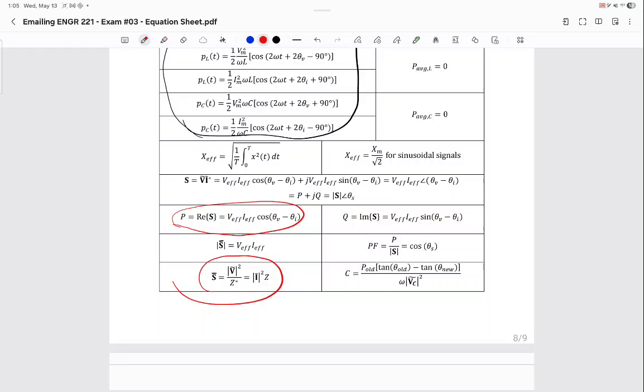Is it very easy to find average power from complex power or no? Just write it in rectangular form and it will be the real part. This is my suggestion. For most of the power questions, I would personally prefer to calculate the complex power. I'm going to do it for the first one and you'll see why.